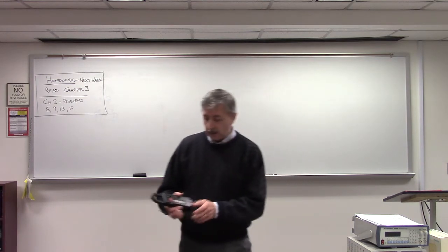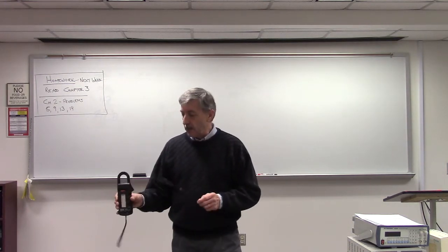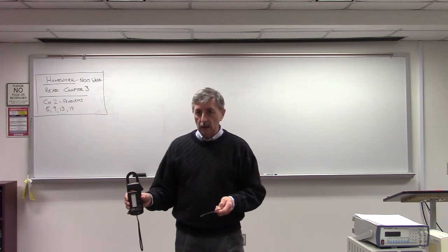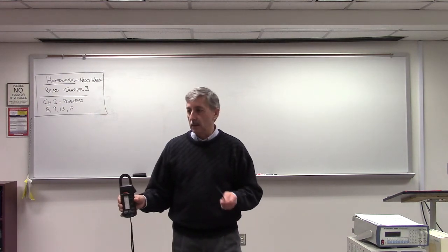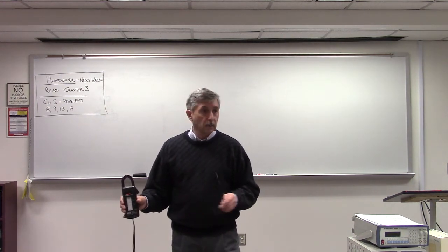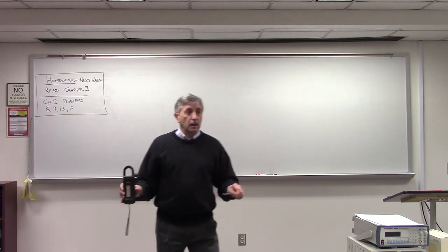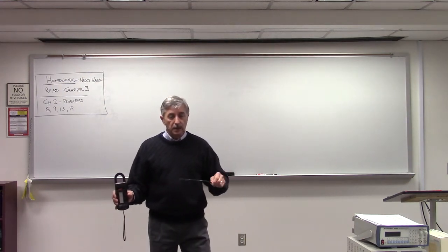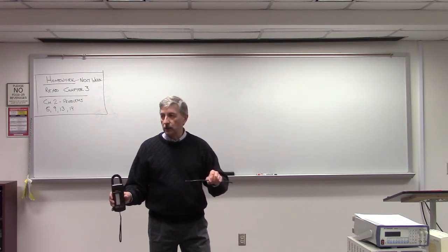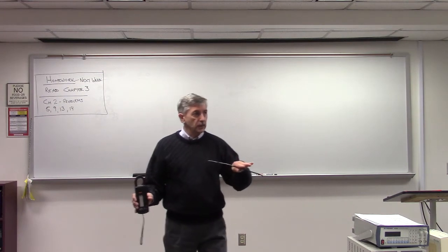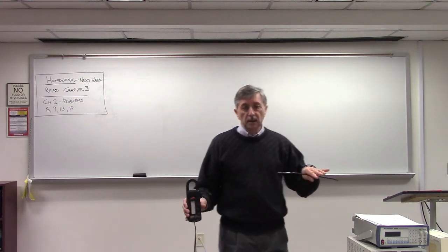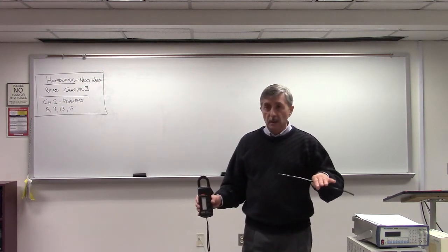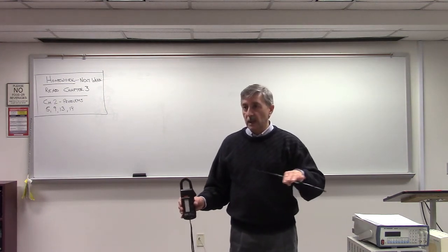The reason I like this is because if I'm measuring the current in a motor, for example, the motor's not running, and somebody flips the switch and starts that motor, the instant that motor starts, just for a second, you'll get an inrush of current that's maybe 6 or 7 times the current that you'd see when that motor is up and running.